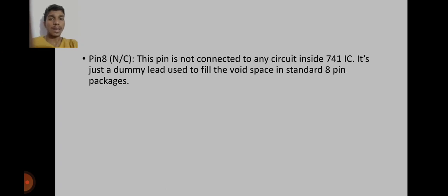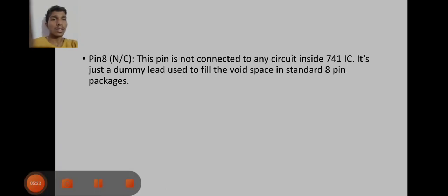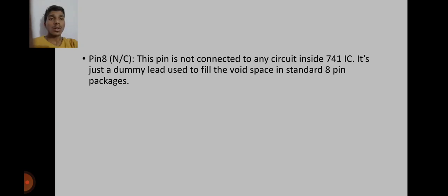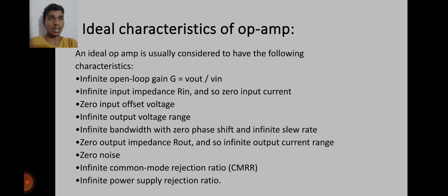And pin 8 is no connection. This pin is not connected to any circuit inside the IC 741. It is just a dummy lead to fill the void space in standard 8-pin packages. We only have standard 8-pin packages, not 7-pin packages, so to avoid the empty space in standard 8-pin packages we are using this pin 8, which is NC, that is no connection.